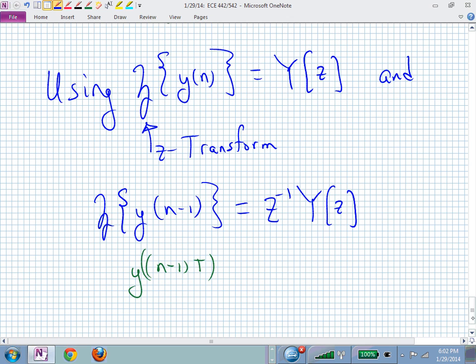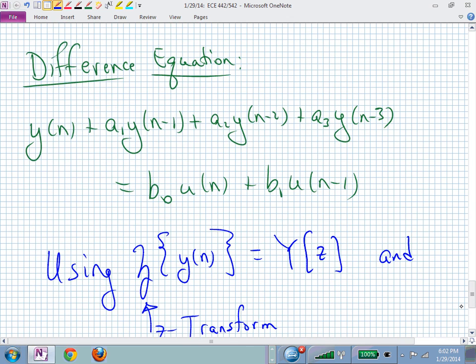This now allows us to immediately z transform that difference equation, just like we could very quickly Laplace transform a third order differential equation. And if we're looking for transfer functions, we don't have to worry about initial conditions. We're just looking at the behavior of the system.